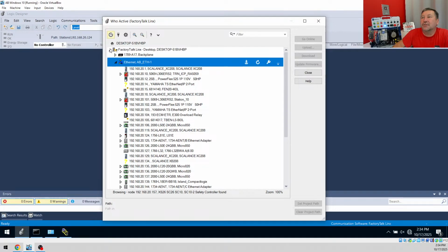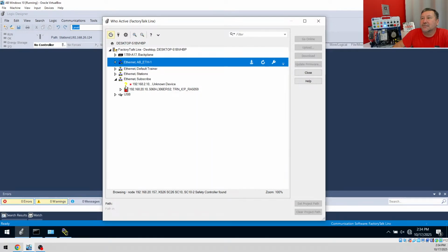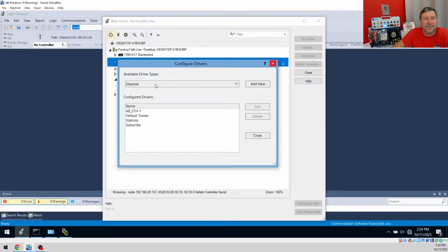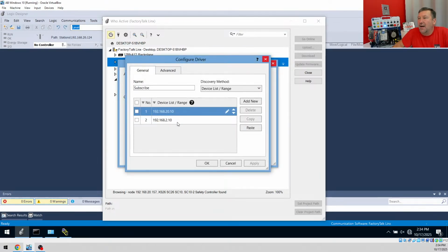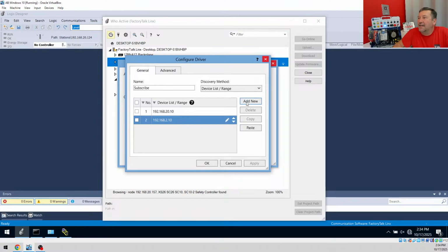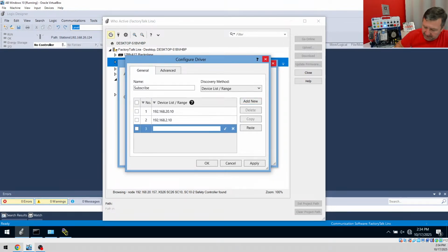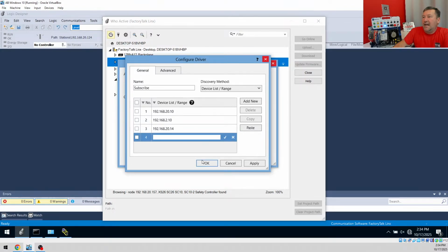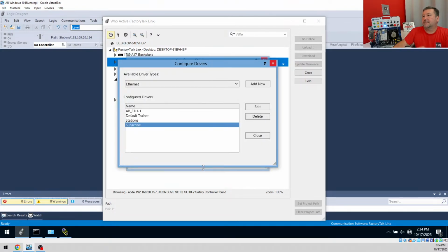So we're going to go back to our configure drivers, and then we're going to double click on the subscribe. And we're going to add another new one. And this one's going to be 192.168.20.14. And we'll go and click OK on that.